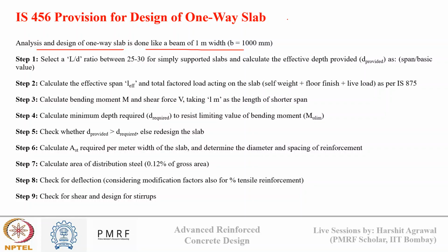The analysis and design of a one-way slab is done like a beam of 1 meter width. So we saw reinforced concrete beam design. The slab design is done in the same way. We divide a slab into different parts as a 1 meter width beam, we design for this, and we assume that it will run throughout the slab.